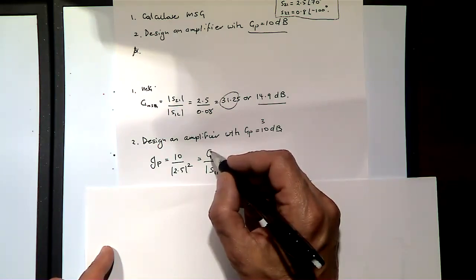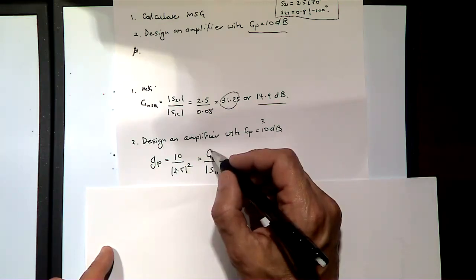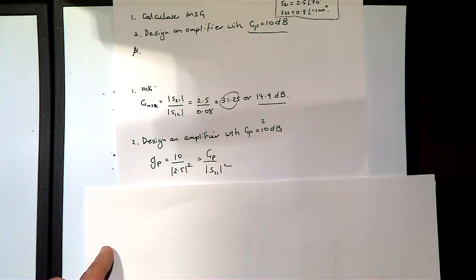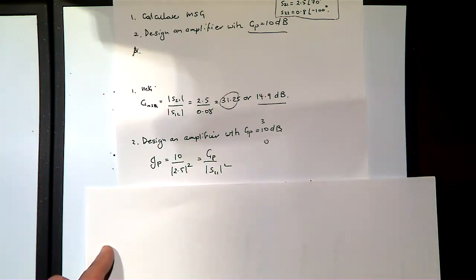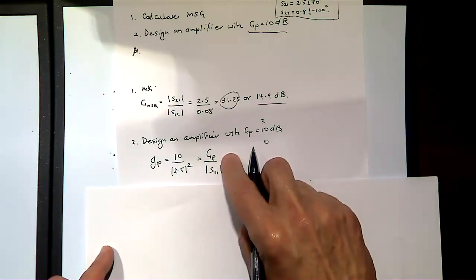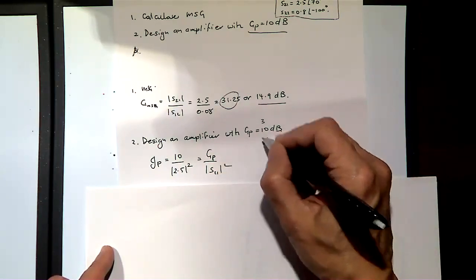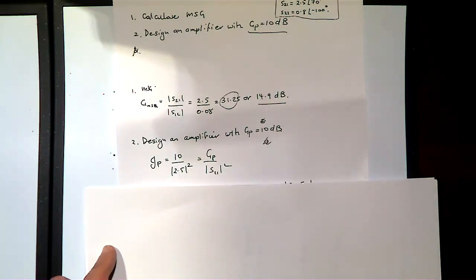Yes. Okay. So everyone realizes what your colleague has just pointed out? You don't put the dB value there. You calculate, you turn it into linear, and then you put that value. Don't put dB there. It's a common mistake. Right? So if this was 0 dB, as an example, don't put 0 there. Put 1. Okay? All right. It's a common mistake. Everything is done in linear scale, right? Don't be confused and forget and leave it in dB.